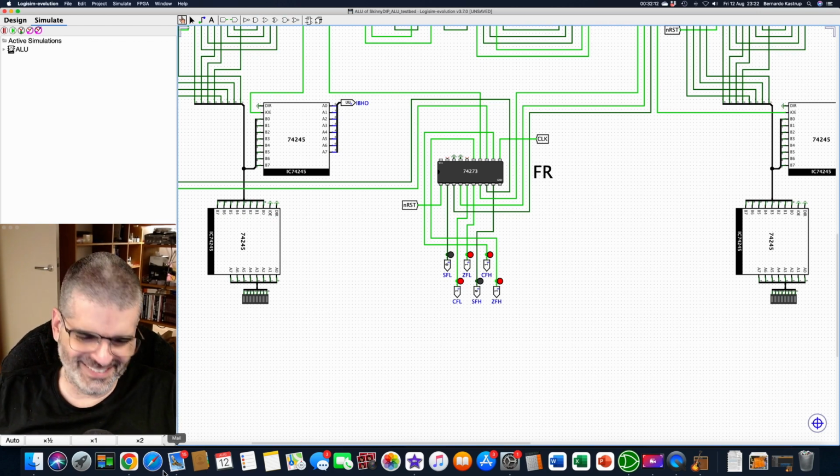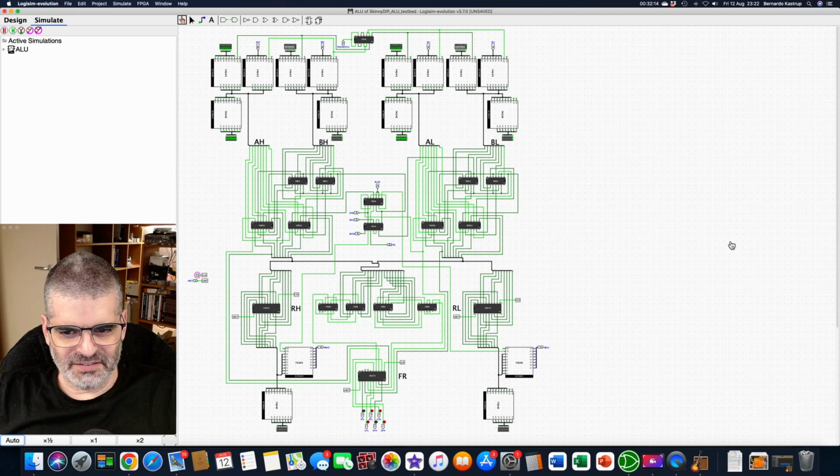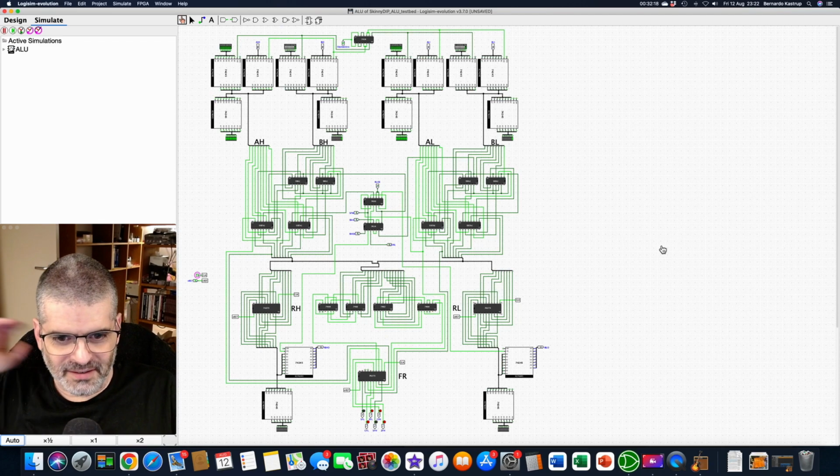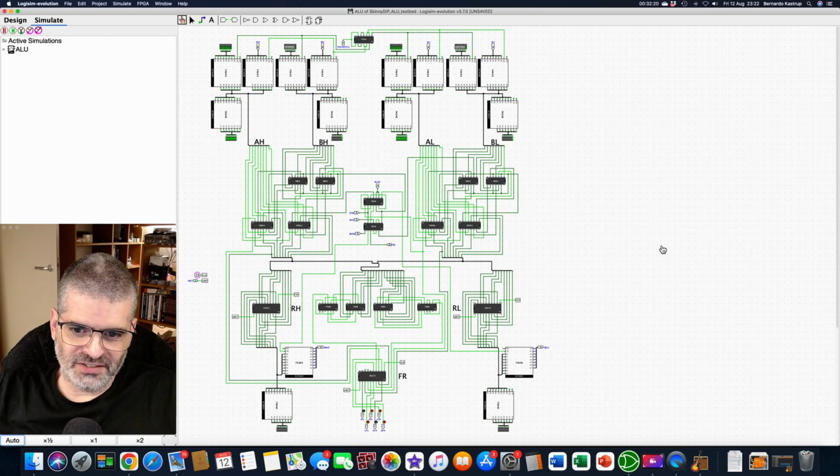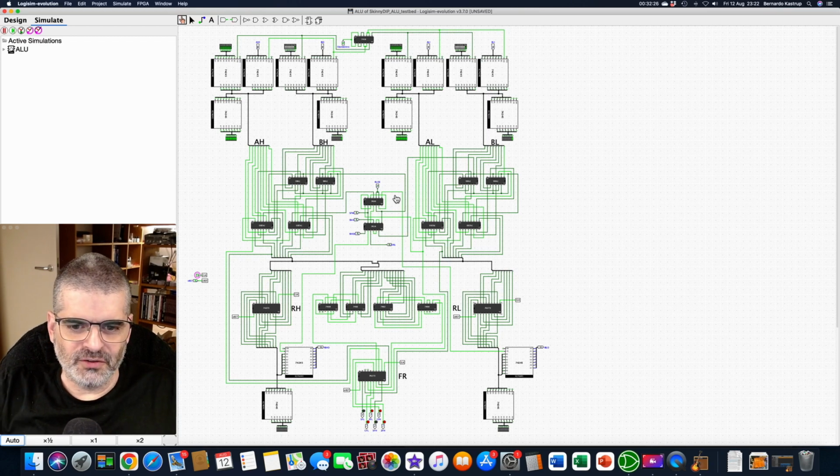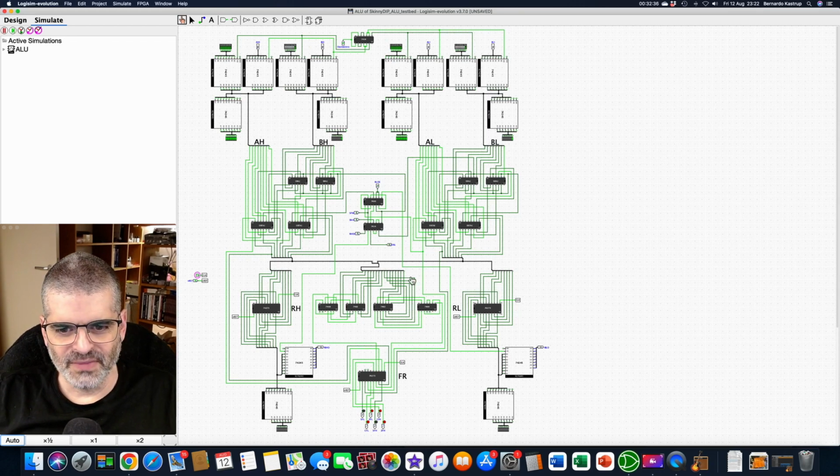It's enough for testing. The point of doing this, as I'm sure I'm repeating myself, but I'll say this again, is I want to make sure that my netlist, my interconnect, is correct, because that's what I'm going to export as a netlist to a schematic diagram and put on the PCB. That's the whole point of this test, is to make sure the PCB will be correct.